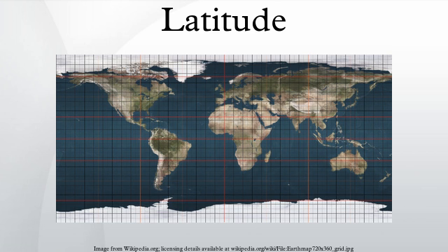Authalic latitude. The authalic latitude, ξ, gives an area-preserving transformation to a sphere, where the radius of the sphere is taken as given. An example of the use of the authalic latitude is the Albers equal area conic projection. Conformal latitude. The conformal latitude, χ, gives an angle-preserving transformation to the sphere, where gd(x) is the Gudermannian function.